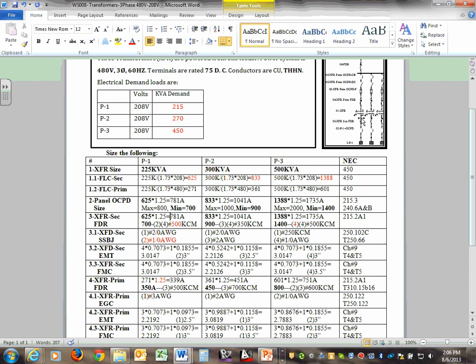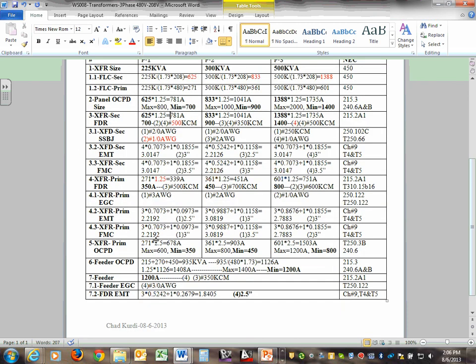But if you're using 1.25, I always say match the overcurrent protection device. I use this rule if I'm sizing my overcurrent protection device based on 2.5, because that's way oversizing your conductor. Okay, so that's my overcurrent protection device, 350. Same thing. You can see we matched the minimum. I use the minimum here for the primary. You can see I'm sizing the conductor based on the minimum.